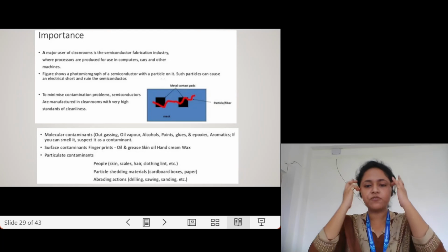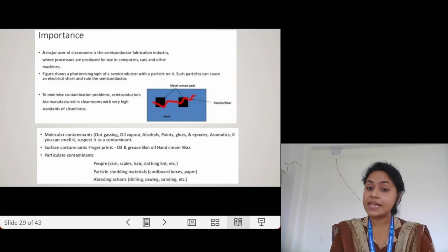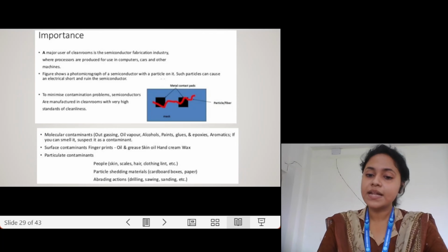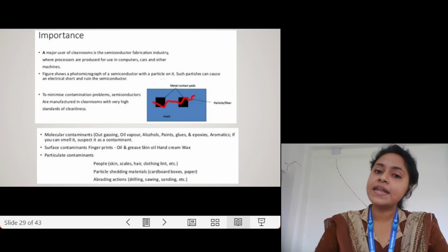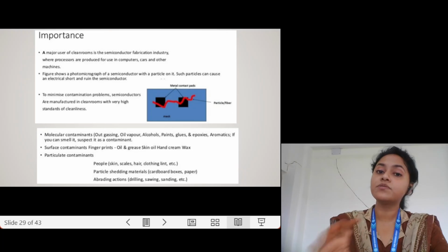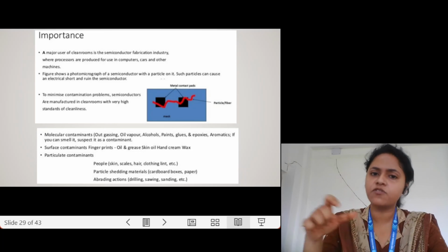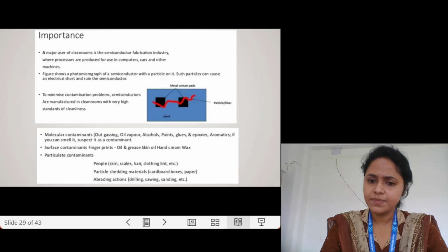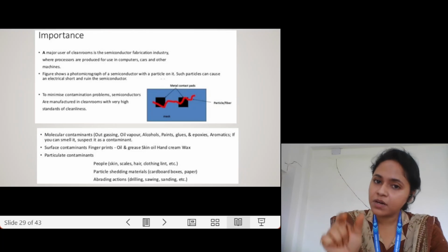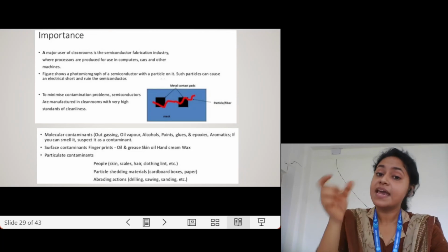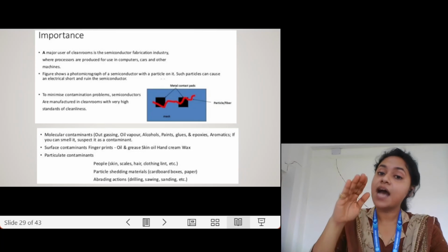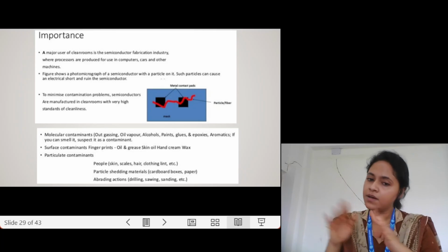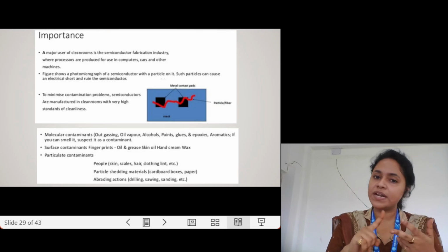Now, I have already mentioned that nowadays in VLSI technology, you might have heard of VLSI, that is very large scale integration. In VLSI technology, what is actually happening? Thousands of interconnect lines, or thousands of MOSFETs, BJTs or FETs are implemented in a single chip. In a single chip of the order of a few centimeters, you can embed thousands of MOSFETs, and each MOSFET has three contact areas: one is source, one is drain, and there is the gate.